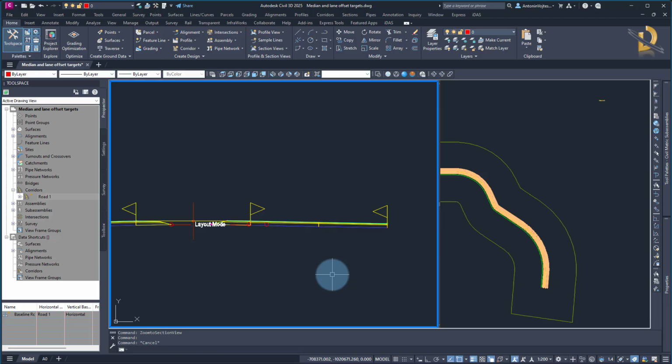Be aware that for some very difficult alignments, the offset alignments might fail. It can happen. So in those cases, you must use other options, maybe polylines or feature lines if it does provide better result. But I'm not going to run this exercise because it is fairly simple and you already know how to do all that.